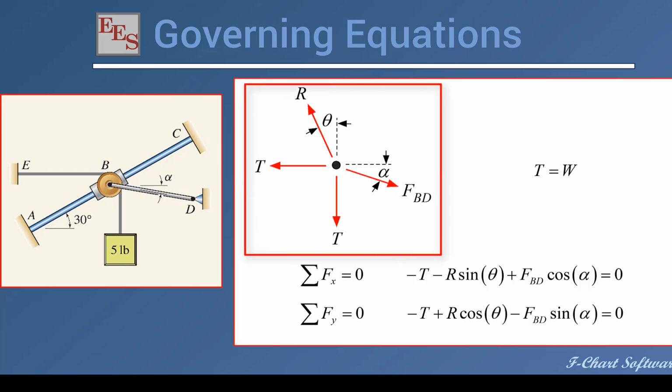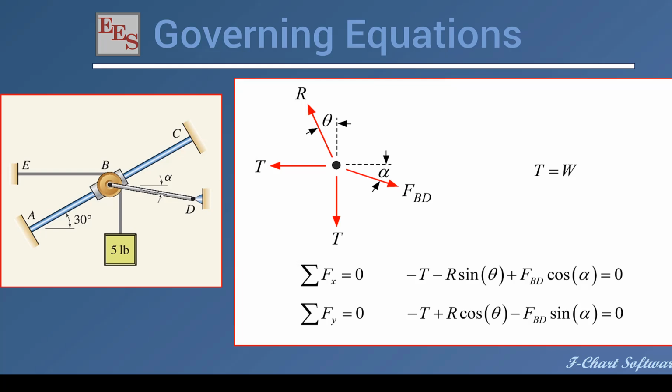The free body diagram basically just says that there are 4 forces on the collar. Right, there's a force due to the cable that is pulling down, and the tension in that cable is just the weight that it's holding if everything is static. So a free body diagram on the weight itself would just say that the tension is equal to the weight.